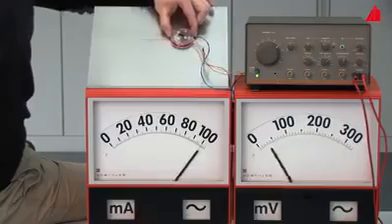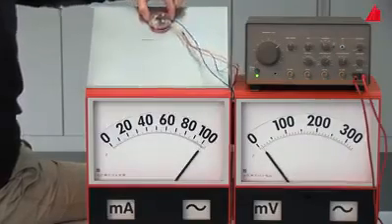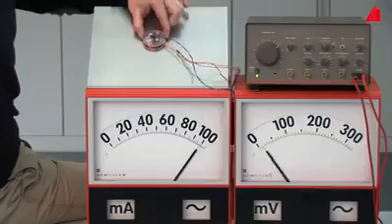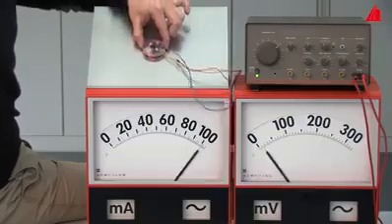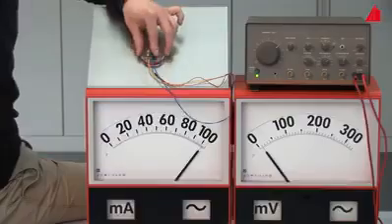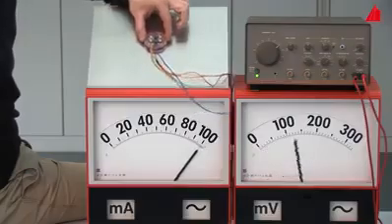But one point should always be kept in mind. The two D-shaped receiver coils must have the correct orientation for saw cuts and cracks. Otherwise you measure only little or nothing at all. If the orientation of cracks is not known, the probe is rotated by 90 degrees after the first pass and the test piece is scanned a second time.